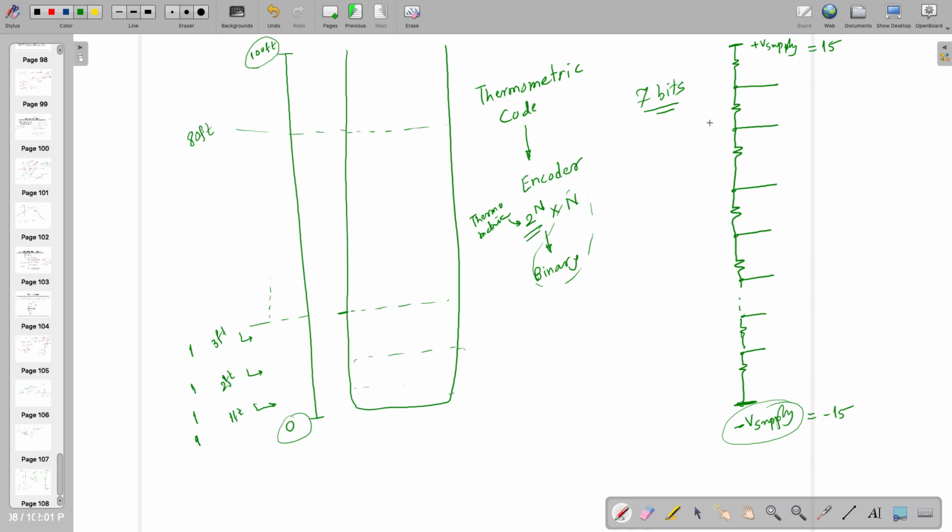So you will have V1 equal to 0.3 volt, because that is already given, 2 raised to n. You need 100, so 0.3 volt is going to give you first, then 0.6, 0.9 and so on, and those are equivalent of these levels.